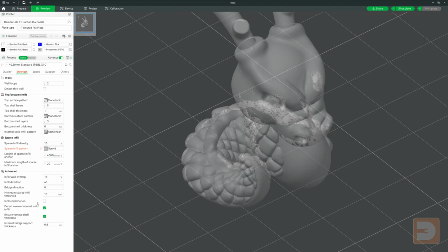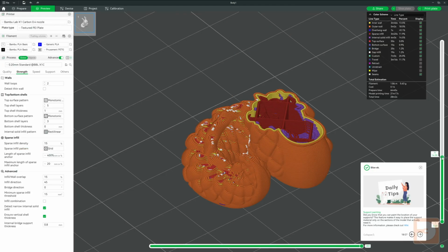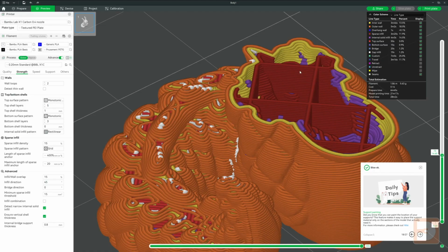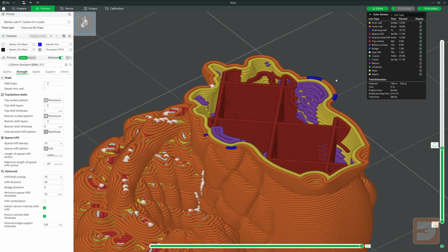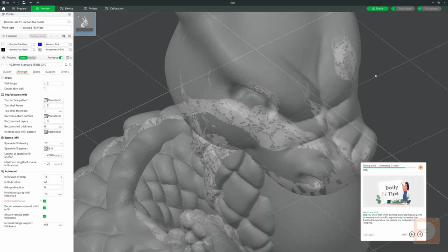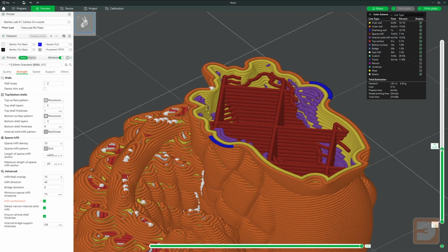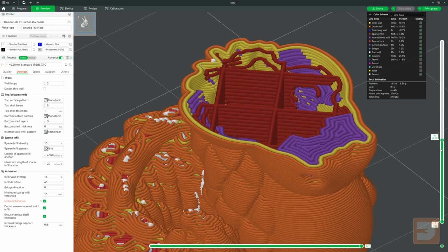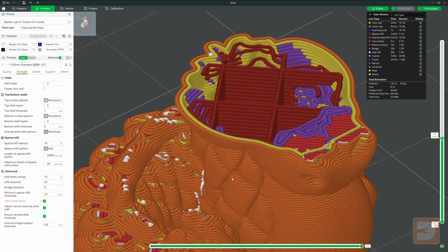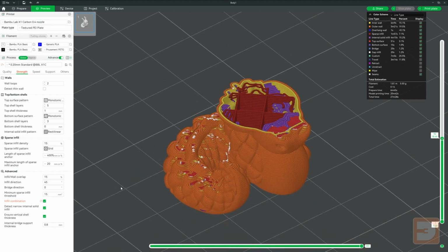Infill combination is a time-saving mechanic. It basically combines several layers of infill and prints them together as deeper extrusion lines, whilst printing your exterior perimeters at the layer height you've set. So let's say you had your layer height set to 0.2mm. Normally, your infill would also be printed in 0.2mm layers with the rest of your print. With this activated, however, whilst the walls are still printed at 0.2mm, the infill is only printed every 2 exterior layers, meaning that the infill is being printed at roughly 0.4mm layer height.